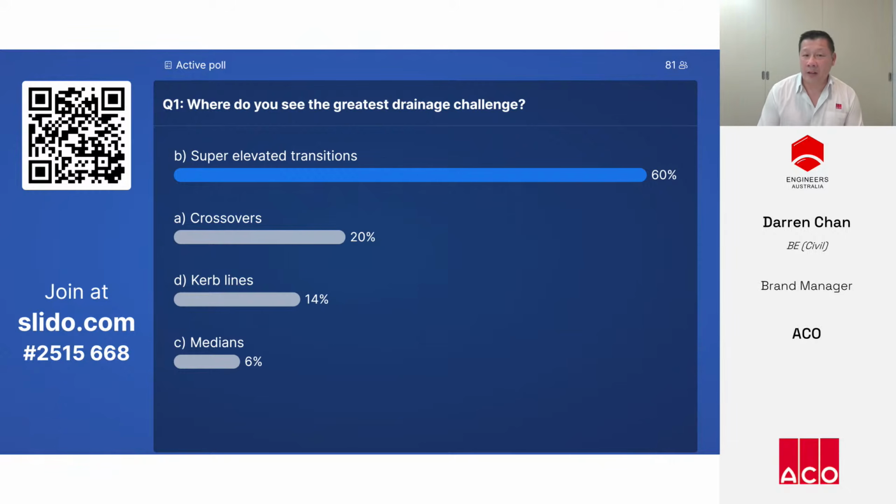So therefore, it's the challenge of putting in a drainage system in the middle of the road amongst all of the other infrastructure in the ground. So that's always been a challenge, and ACO have come up with some good solutions, and we understand those solutions. We've continuous capture inlets that Kate presented with curb drains and graded trench drains that are used in those areas.